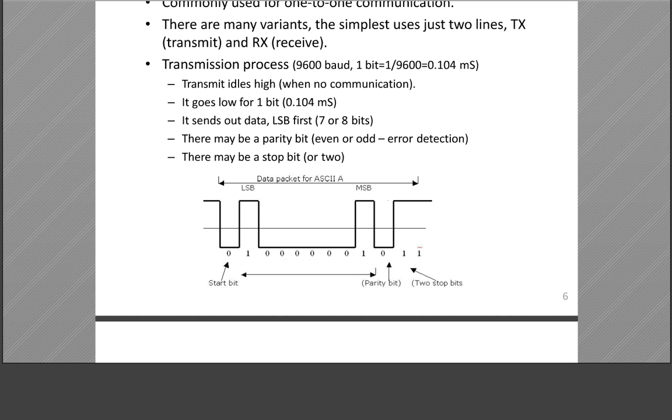Here we have 2 ones, which is even. Thus P must be 0. The sum of ones in the packet and the parity, all of them must be even in even configuration.